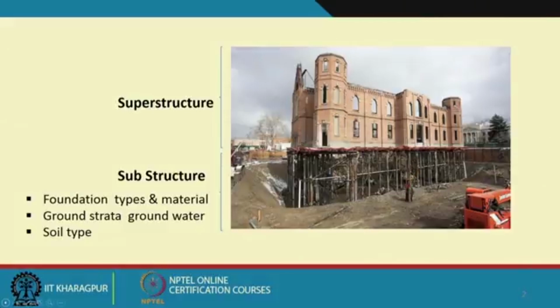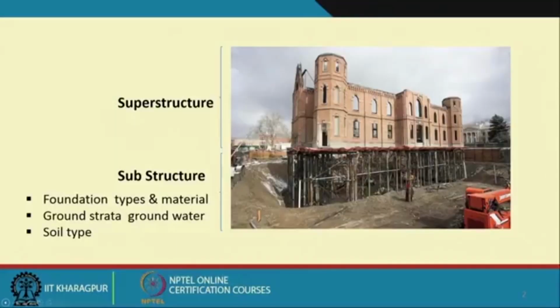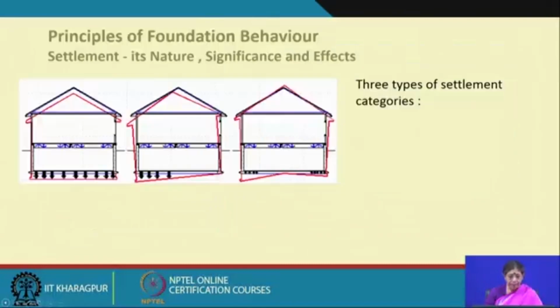So, we have to remember these two parts, and they are very integral. You can imagine that when we are talking about a historic structure, understanding the substructure is not easy, because it is always covered. Sometimes there is development around the structure. So, how do we understand that, and how do we take certain mitigation measures? They are a very important part of understanding any repair measure.